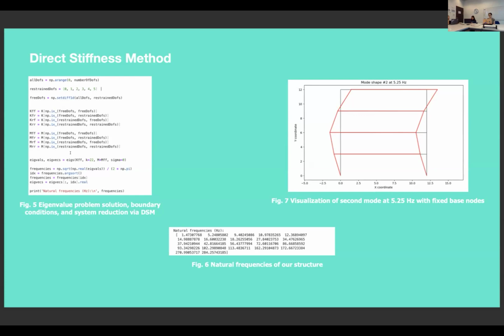So this method takes more into account the complexity of our four-story building, because we will have more degrees of freedom to take into consideration. We will have 3 degrees of freedom per node, compared to the previous implementation, which was very simple because it was just defining the system as a discrete system of punctual masses per story.